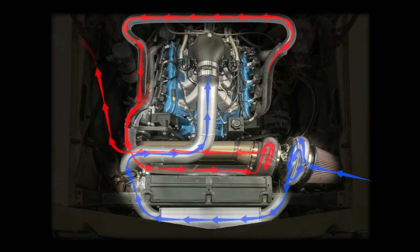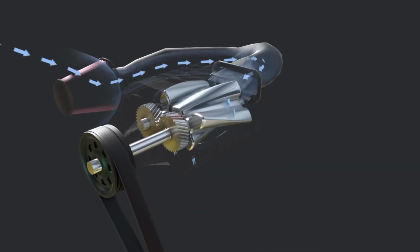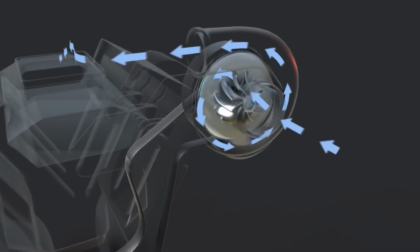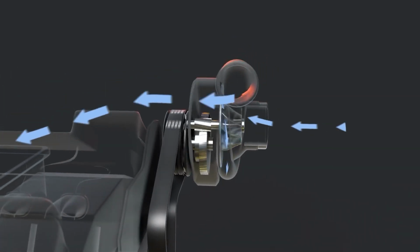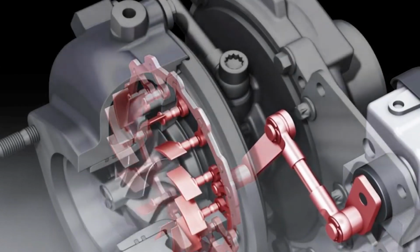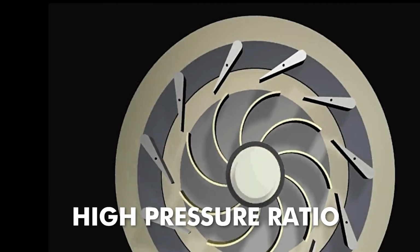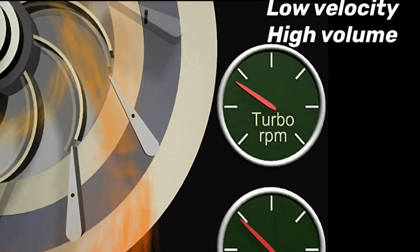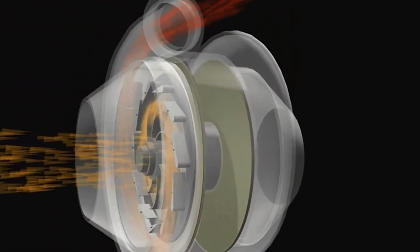Next, the air enters the compressor diffuser, a vaneless, diverging passage that converts the high-velocity kinetic energy of the air into pressure energy by slowing the airflow. The compressed air then collects in the volute, which further helps maintain steady pressure as the air flows out of the compressor housing and into the engine intake. The design features such as inducer diameter, diffuser shape, and volute size are optimized to achieve a high-pressure ratio and maximum flow with minimal losses, allowing the turbocharger to deliver dense, pressurized air to the engine for combustion.